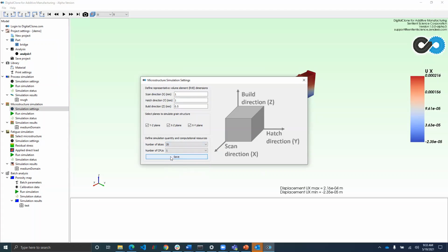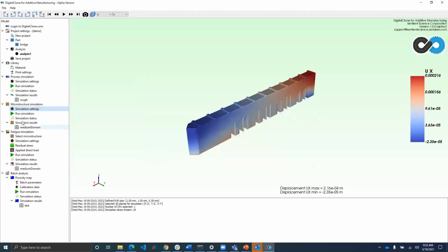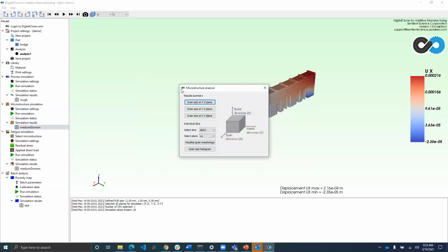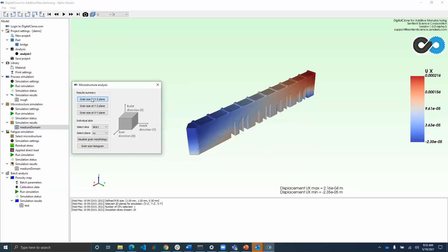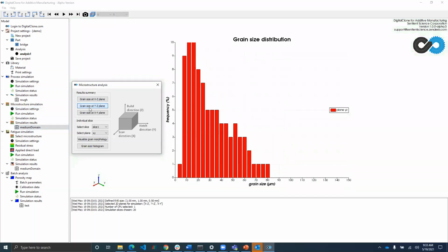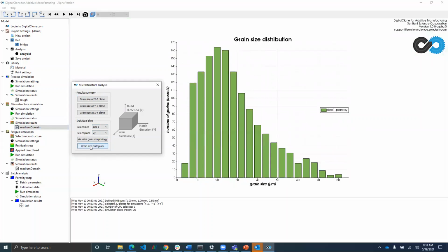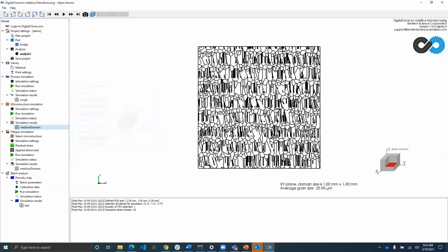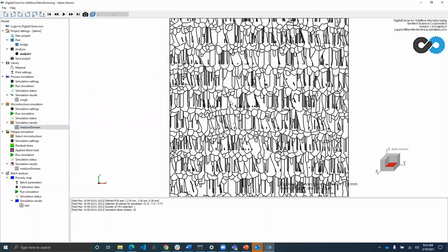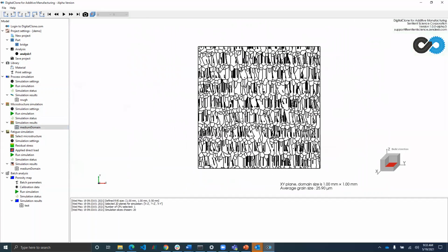this randomness. In post-processing, the user is able to see the grain size distribution measured in each plane for which a simulation was requested. Furthermore, for each individual microstructure that was generated, the user can see the grain size histogram in addition to a view of the grain morphology. The grain morphology plot is furthermore interactive, so the user can explore and experiment with the microstructure.